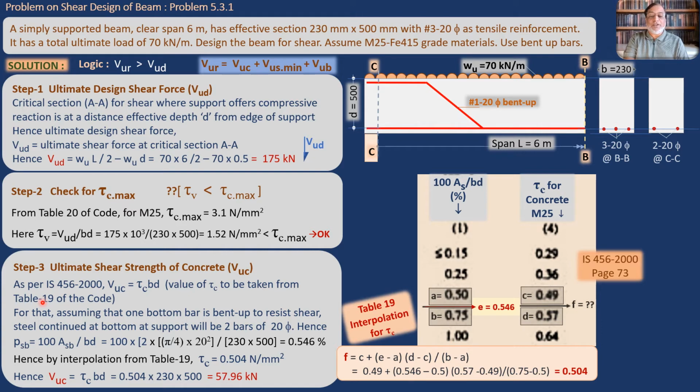Now here, as we saw in the earlier video also, the value of AS is to be calculated with care. The value of AS, area of steel, is the value of area of steel available at bottom at the critical section or at the face of the column or support. It is not the area of steel available at the center. If you look at these two sections, we find that we are having 3 bars available at the center of the beam, whereas we have got 2 bars available at bottom at the face of column section where shear is critical. So IS code is saying you don't talk about those bars which are at the center, you talk about the bars which are available at bottom at the face of the column or at the support where shear is maximum. So this AS is in this problem 2 bars.